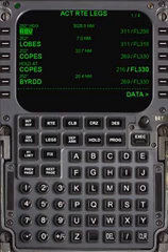The cost index is calculated by dividing the per-hour cost of operating the plane by the cost of fuel. Generally, a cost index of 999 gives econ speeds as fast as possible without consideration of fuel, and a cost index of 0 gives maximum efficiency. Econ mode is the VNAV speed used by most airliners in cruise.